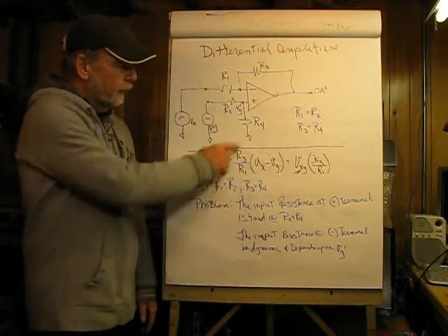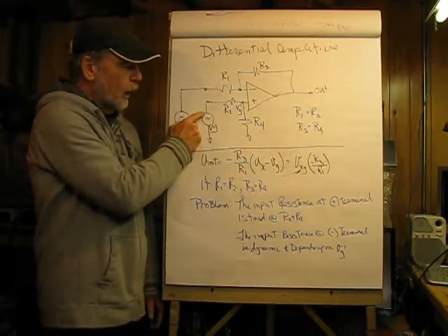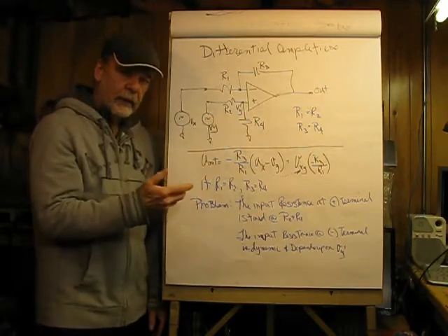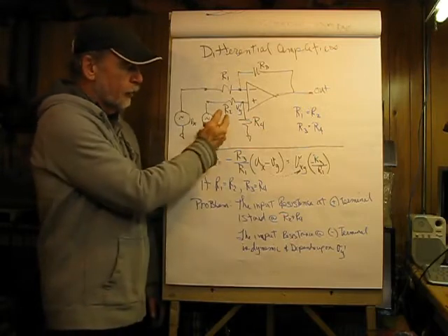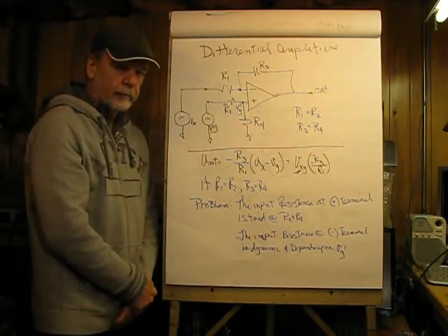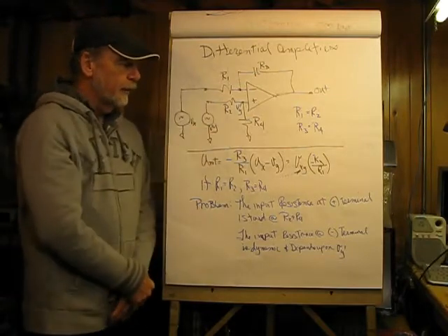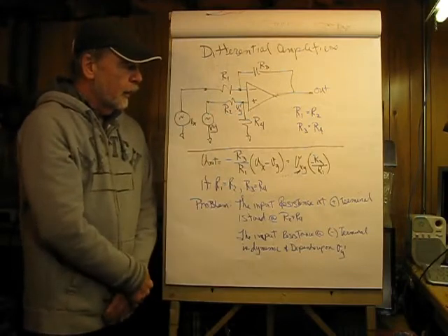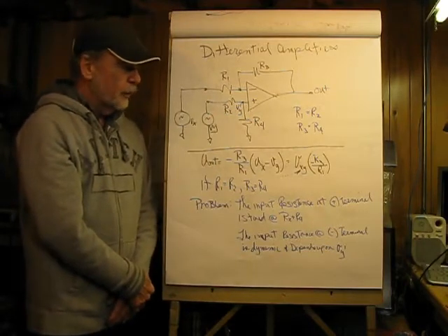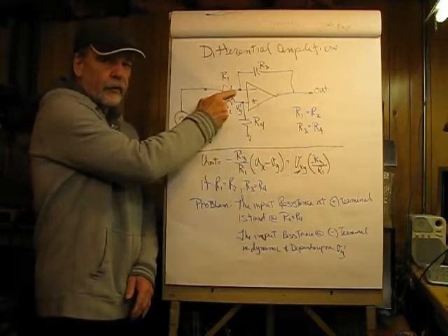So if we take a look at this guy, this is the non-inverting input. Vy is always going to see a constant resistance here, which in this case is just going to be R2 plus R4. Now the inverting input, this is quite different, and what we have here is its node voltage of V prime Y is basically going to determine what this source sees at this.